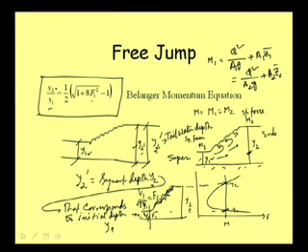So, that relation we will be getting. We are writing m1 equal to m2, and this implies that this is equal to that. Knowing that, suppose for a particular known initial depth y1, we can calculate the area, then we can calculate the z bar also based on the section. If it is trapezoidal, we can find the z bar, that is the average depth up to the centroid of the area.